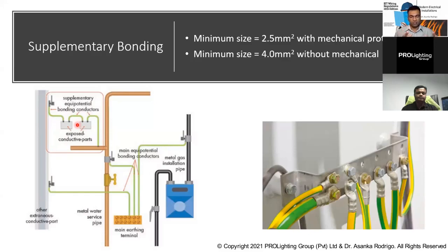Because nowadays, and I'm coming to that, we are talking about the three-dimensional earthing arrangement, or an earthing mesh kind of arrangement where everything should be connected together, so that only then can we reduce the voltage related disturbances as well as the electromagnetic interferences. To achieve that in the modern building, all these are recommended nowadays. Of course, you have to have a protective conductor and the bonding, but it's better to go with the supplementary bonding as well.